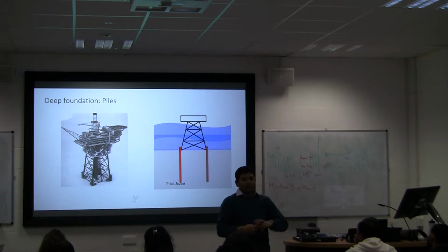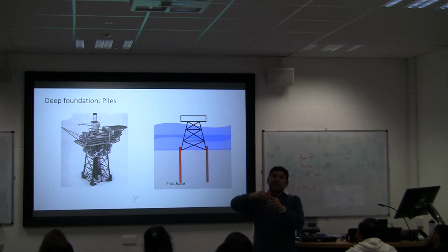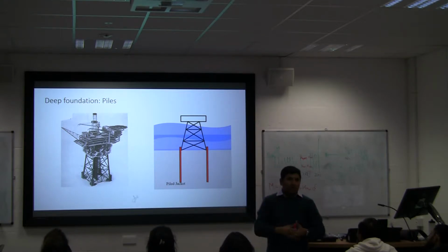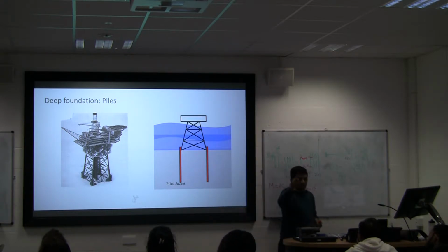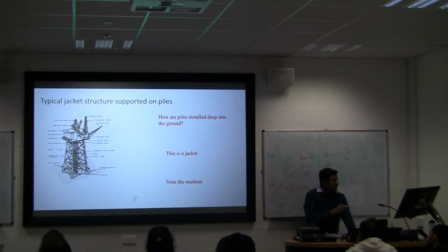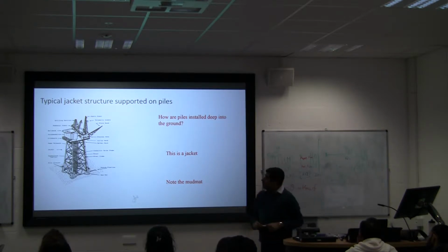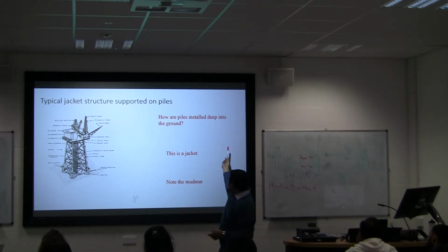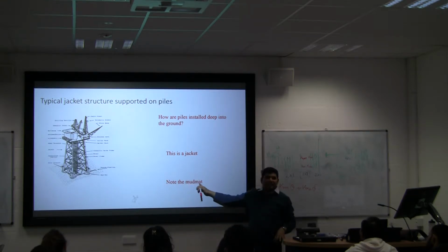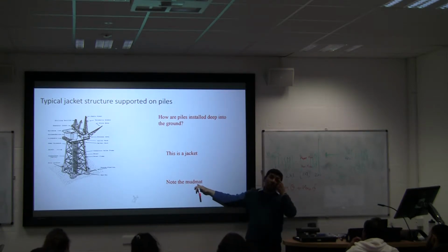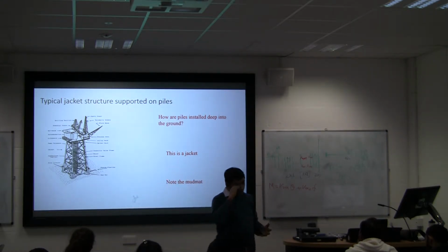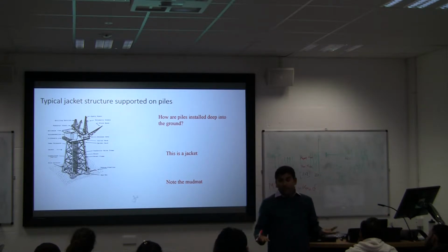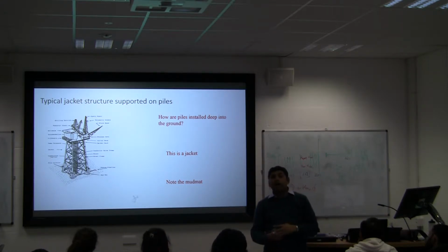Once they have the pile driven, there will be a gap. There they would put a grout around it, grout to hold it all together. Now, so how they install the jacket, note the mud mat. So that is the foundation. That's the shallow foundation. You have a large steel plate, right? And that acts as a shallow foundation temporarily when you put the whole pile in the ground.